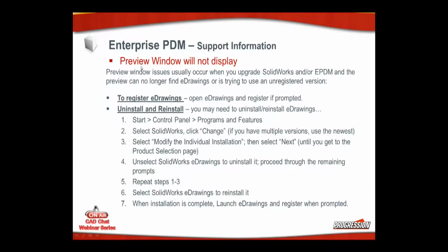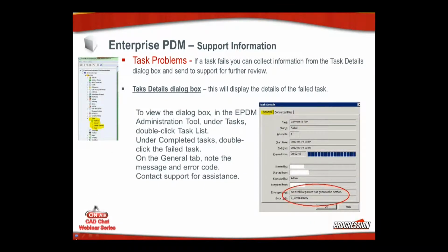Now with preview windows, sometimes the preview window in EPDM will not display previews. Two things that could be happening: the eDrawings is not properly registered. And that's an easy fix. You just open eDrawings, and if it's not registered, it'll prompt you to do so at that time. You could also do an uninstall and reinstall of eDrawings, and here are the steps listed that you can do to do that uninstall, reinstall.